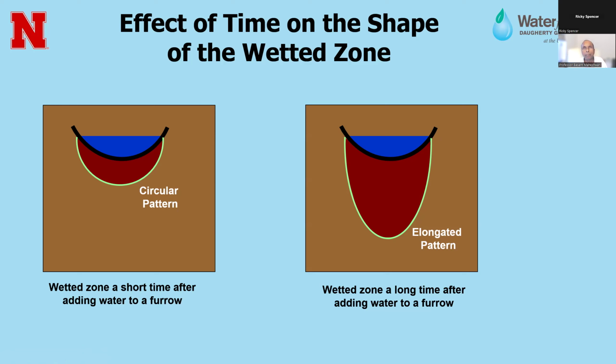That helps us in how we apply water and make water available to plants. We don't want to apply more water than what is stored in the root zone. If we have a sandy soil, we need to be conscious that a significant amount of water can move below the root zone through this sort of pattern, and that can be wastage of water. By understanding how water moves in the soil, we can reduce water wastage.